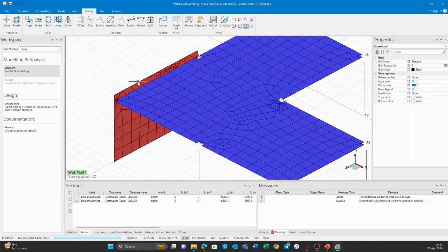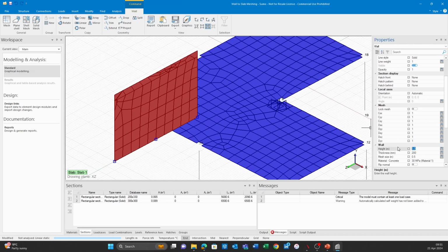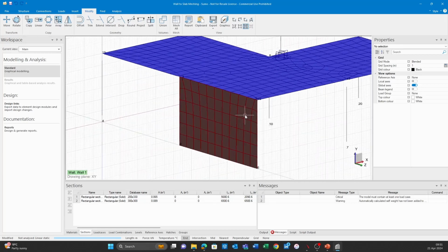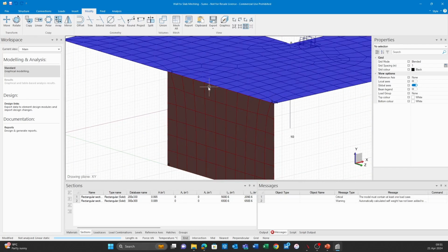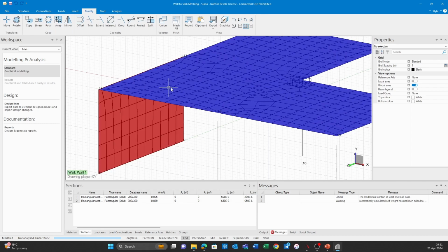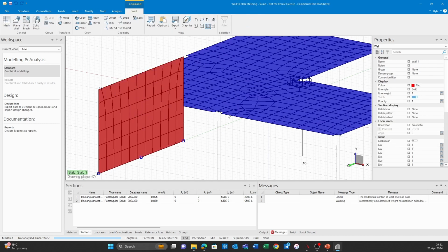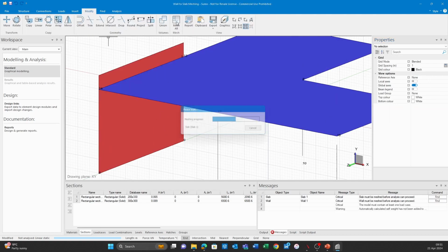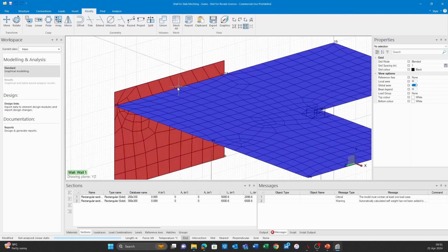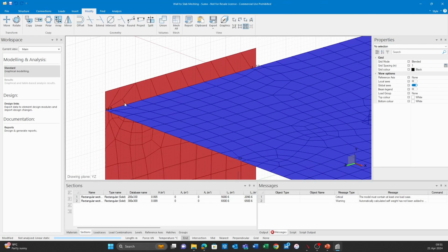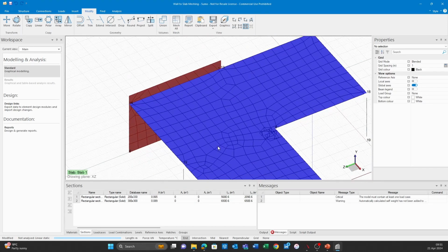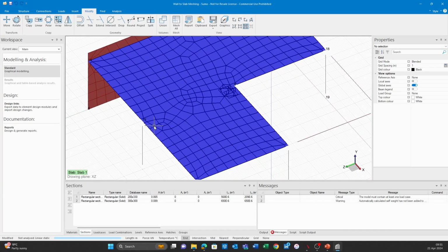So you have two options. Either you reduce this wall height to the height of the slab. Just mesh again, and you see that it's much better, and this edge will be a lot more stable because the slab does connect into that element. Or you extend it a bit more so that it extends the height of the mesh above the slab, and that will be 3.5. Again, this doesn't look fantastic, but it will be more stable along that edge. And the same applies if you have walls coming through the center of the slab or anywhere else; you want to approach it the same way.